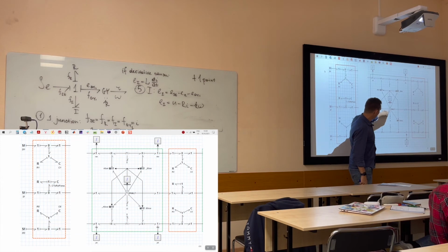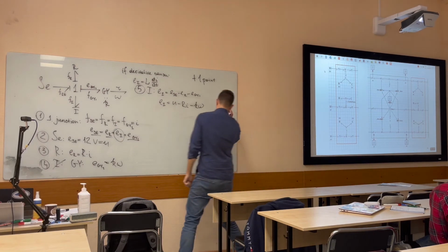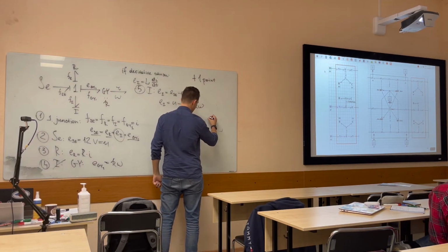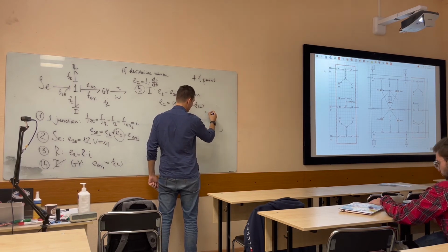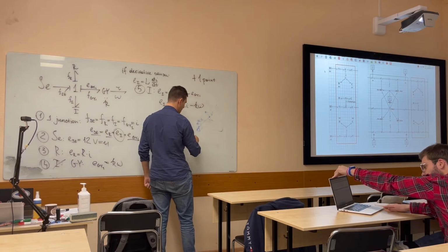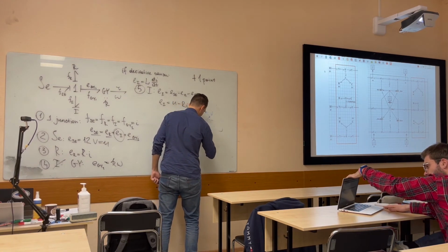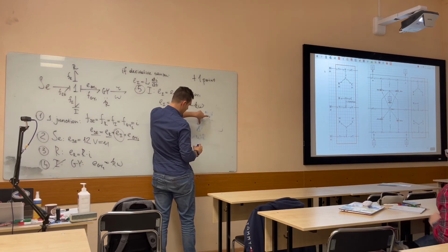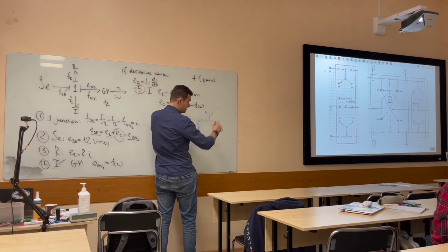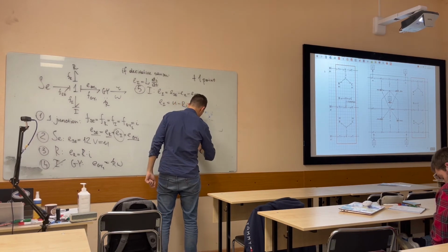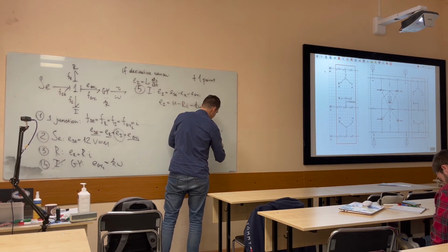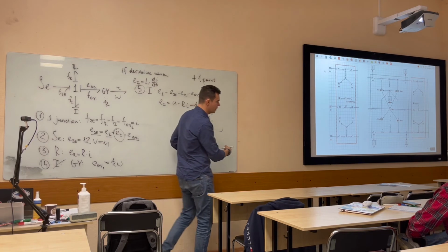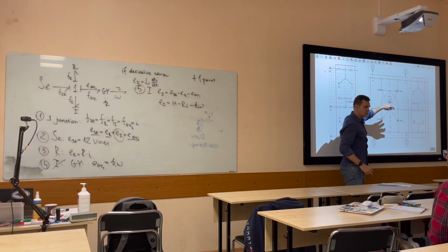And here you do have angular velocity. Let's assume that you have one link and you know its angular velocity. You can calculate the linear velocity right here. It will be angular velocity times r. Since there are x and y components, there will be v_x equal to v times r times cosine of the angle, right? And this stands for y. And this is why it looks so complicated.